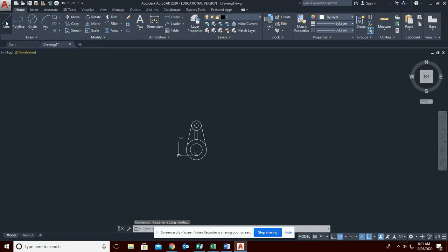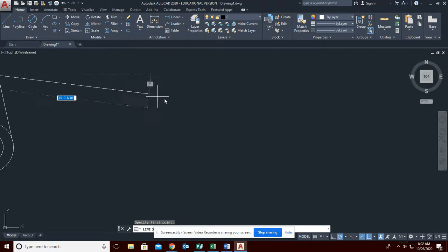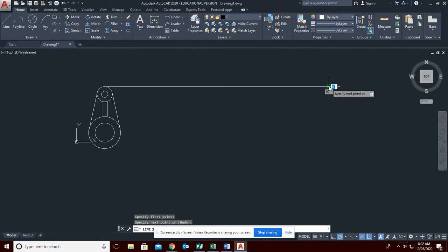Now, these other views will get a little difficult, and I'll show you how we can get some of these measurements. And I'll show you probably the right side, and I'll let you guys develop the top by yourself. So a lot of these measurements, especially vertically, are already done. I mean, you just measure them out. So I'm just going to draw lines straight over from the exact center. That means I'm snapping to the quadrant of the circles.